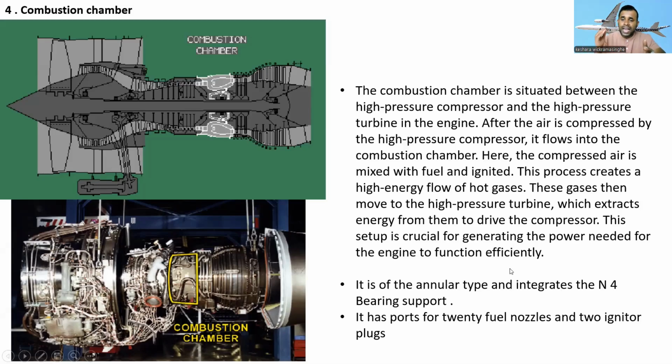It is of the annular type and integrates the N4 bearing support. It has ports for 20 fuel nozzles and 2 igniter plugs. Remember, inside the combustion chamber there are 20 fuel nozzles and 2 igniter plugs. Okay, just remember.